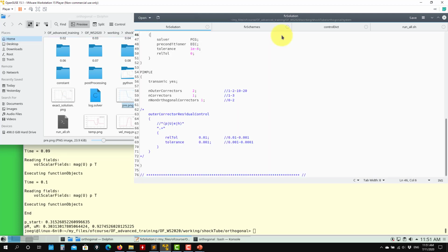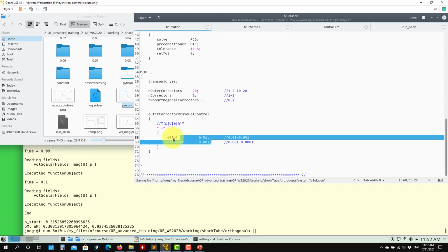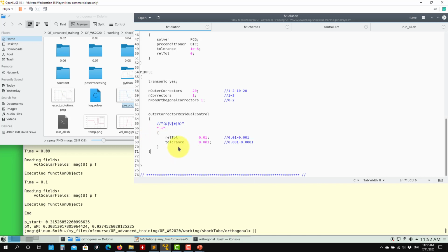So again, my recipe, probably this will be the final one. When you have severe coupled physics like this one, enable at least 2 correctors. Also, you can enable the convergence of this outer loop, so then you will define your tolerance, absolute and relative. Usually I play like this: sometimes I start at the beginning with 2, and then I let it run.